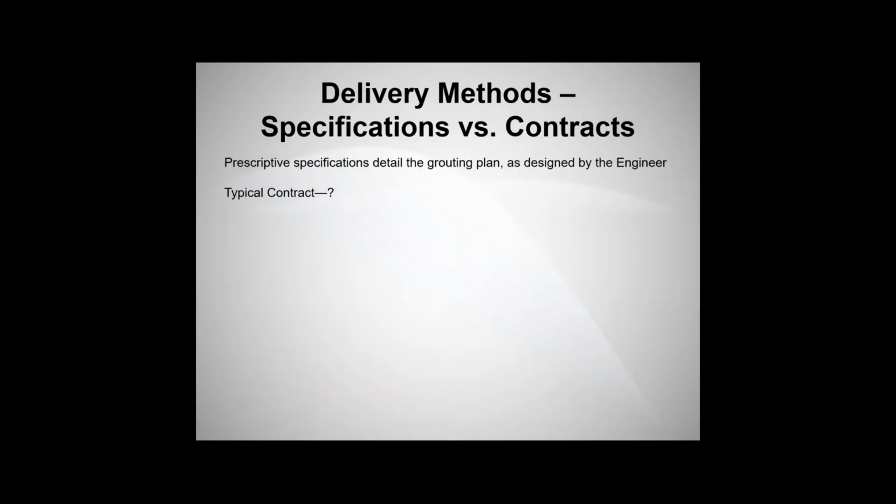So with that, we do need to touch a little bit on specifications and contracts. When we're talking about grouting programs, a lot of times we use what are called prescriptive specifications. That's where the engineer comes up with basically the entire grout design. We're coming up with the grout mixes, the whole layout, the methodology, the refusal criteria. We're basically laying out the entire design.